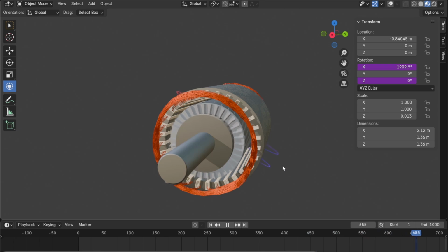And the sad thing about this is that, if you have a burnt connection, it creates a positive feedback loop. The burnt connection will heat up more and it gets worse. And then the motor responds by drawing more current from it. And then the burnt connection gets even worse. And it becomes this loop where it eventually destroys the connection entirely and the wire breaks down enough that it can no longer conduct.